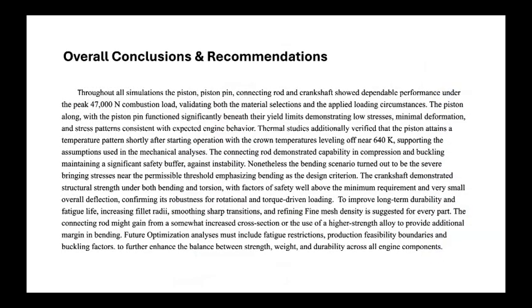Overall, all four components performed safely under the peak 47,000 Newton load combustion. The piston and piston pin operated well below their yield strengths. The connecting rod performed well in compression and buckling, although bending proved to be its most critical load condition. The crankshaft showed excellent resistance to both bending and torsion.